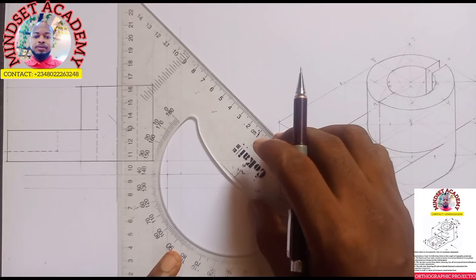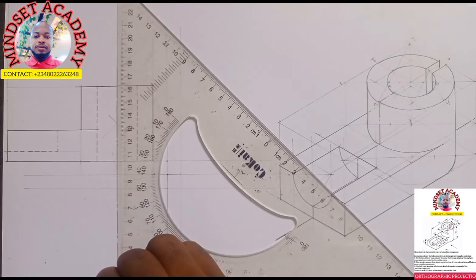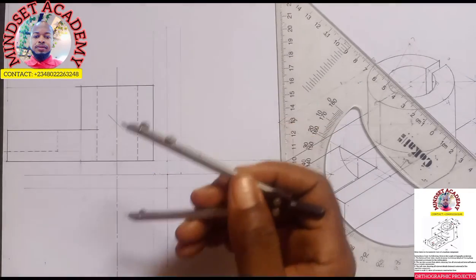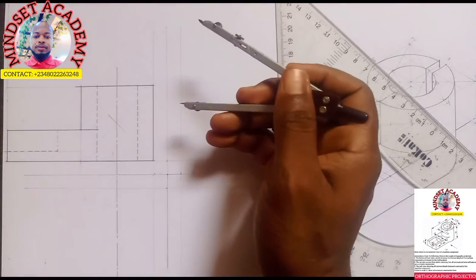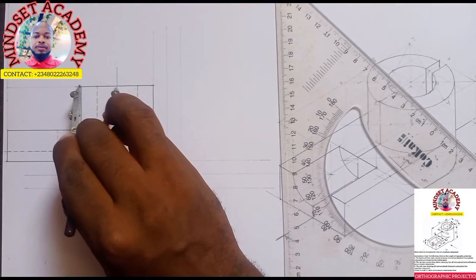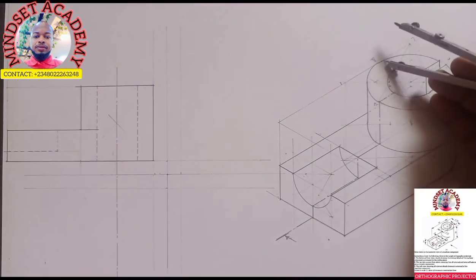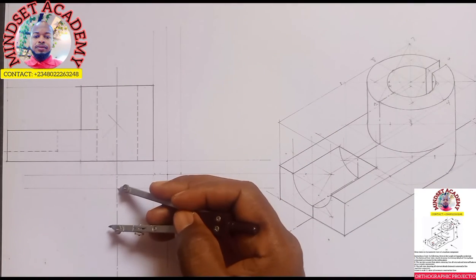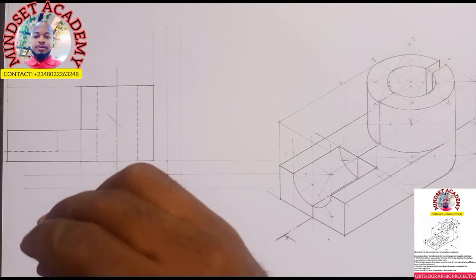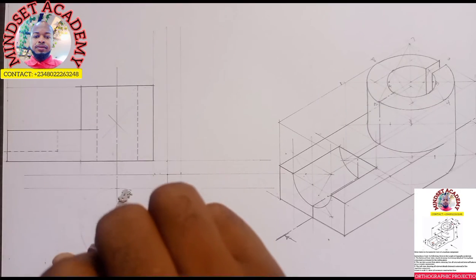I will just from here take this down as my center line. Long, short, long, short, long, short. Right? The same radius as this from here. Because the same thing looking at it from the top, you see this circular figure here. So I can just place it here and I'll mark here so that I can easily get my circle, which I'll just use faint line first.